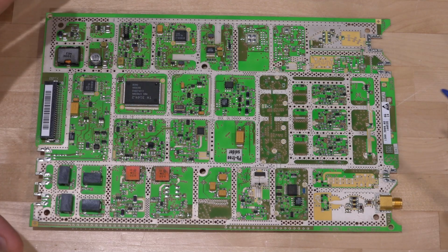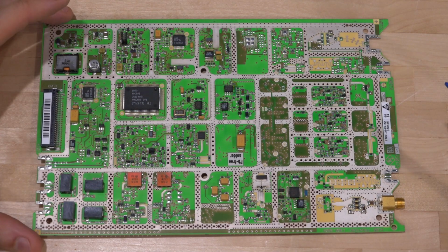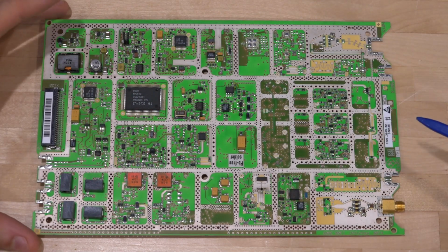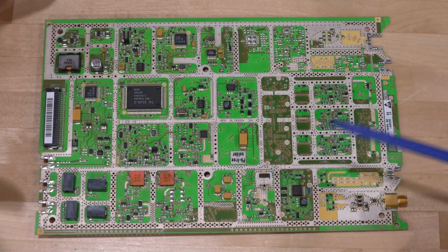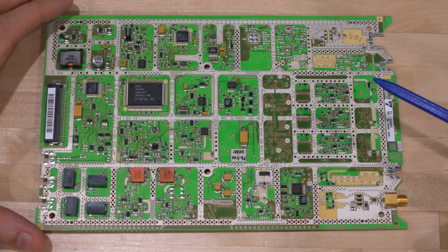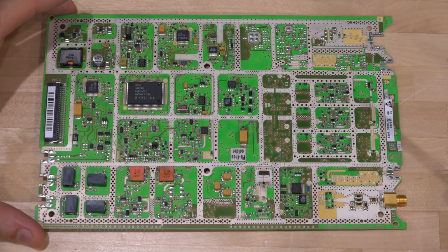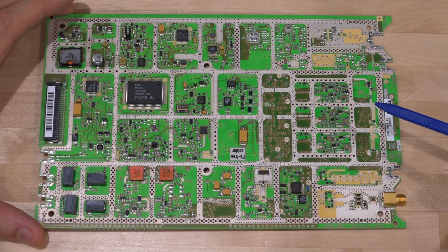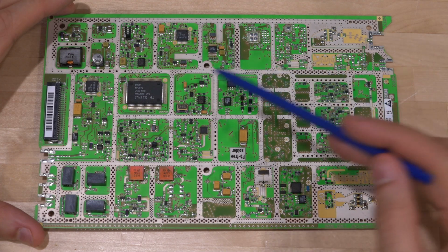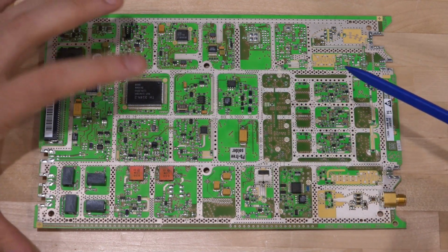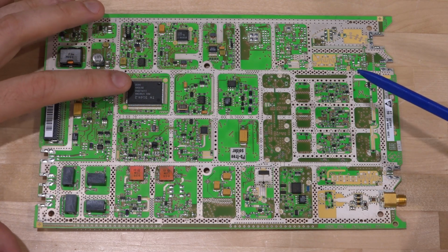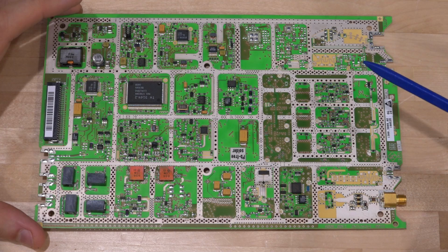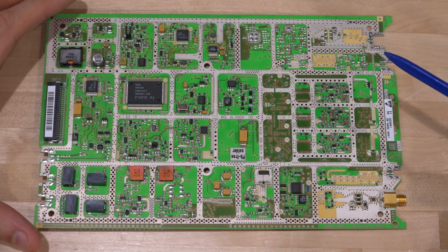So we know what the problem is. We know the issue is this LO unlock we need to look at first. We can go ahead and analyze this and reverse engineer. But the overall architecture of all these is fairly similar. They're all superheterodyne, with multiple LO conversion stages. They do this for various reasons, which I have talked about quite a bit in the past. And some of these I see are Rohde & Schwarz branded chips, so we're never going to be able to find a replacement for these, and we probably won't even find a data sheet for them. But nonetheless, we can explore this.